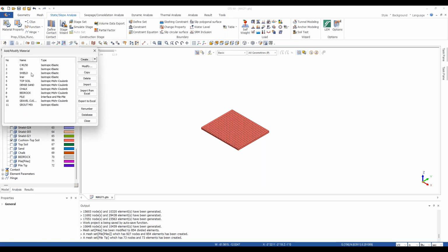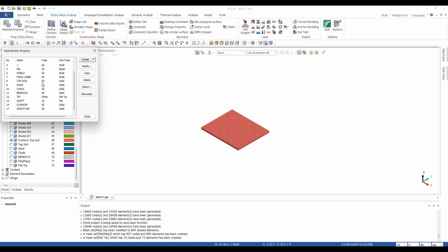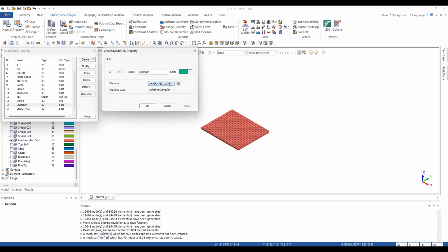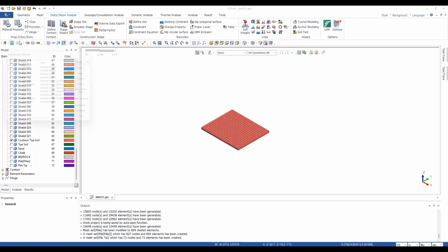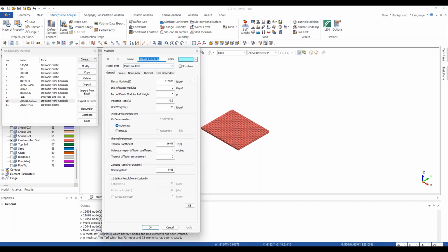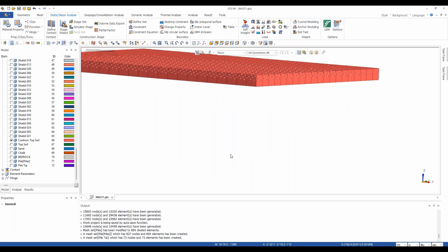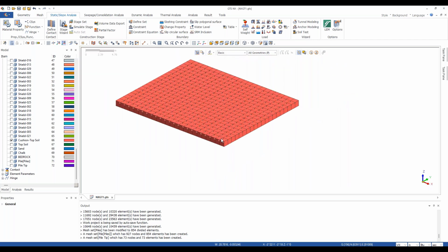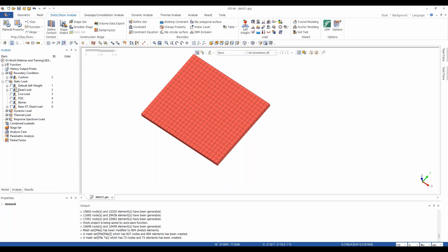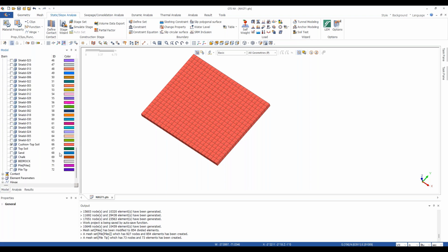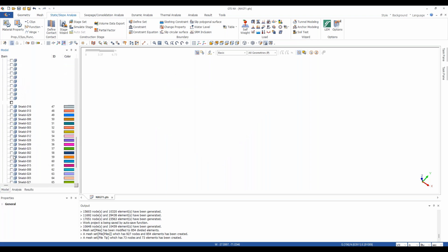If you see here, the cushion properties would be, I'll just check, modify here, the gravel. So I'll show you the gravel cushion. See here, these properties are quite different from the topsoil layer. Now you can see there are red dots here, which indicate the boundary conditions have changed, so that you can visualize it here. If you see, the boundary conditions of this have changed. Similarly, I need to do it for the grouting as well.